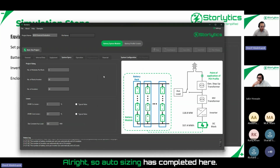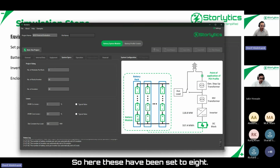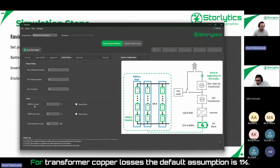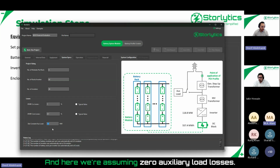All right, so auto sizing has completed here, and you'll notice that all the parameters in the other tabs have been filled out. Under system specs here, the number of modules per rack has automatically been set to 8 modules per rack. So here, these have been set to 8. The number of racks per inverter to 42, and number of inverters for the project has been set to 30. You'll also see that the losses have been specified. For transformer copper losses, the default assumption is 1%. For core losses, 0.1%, and here we're assuming 0 auxiliary load losses.